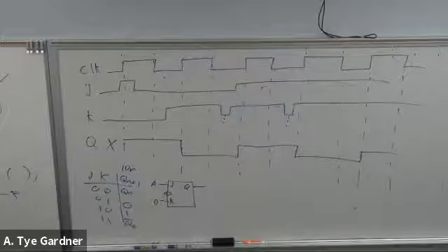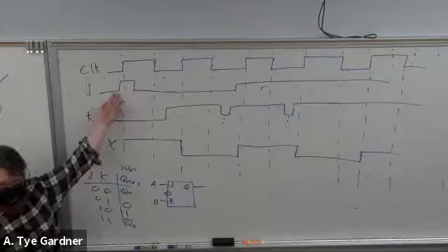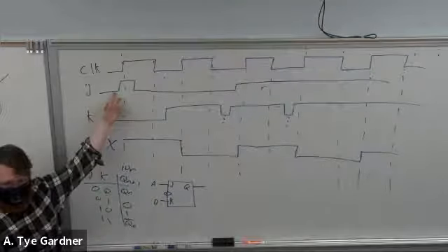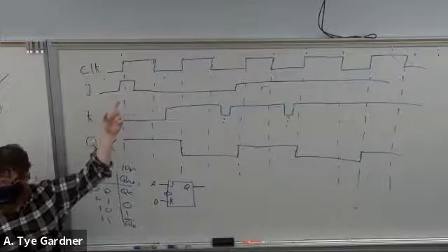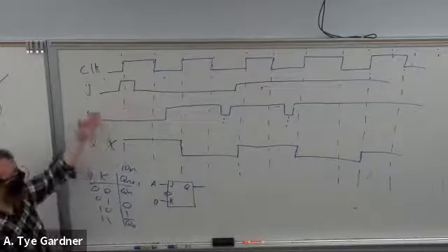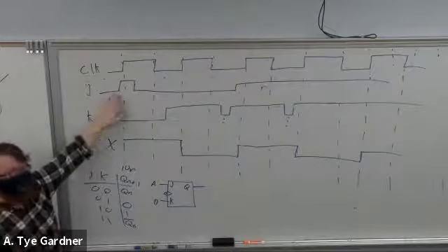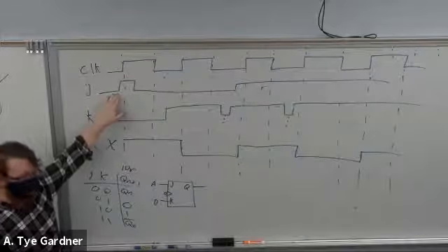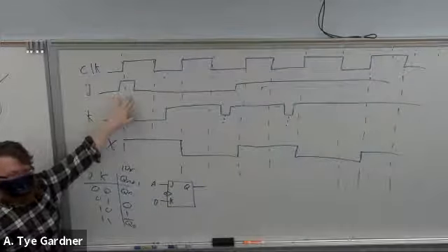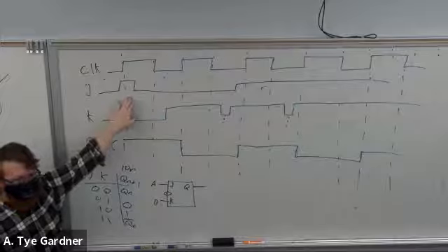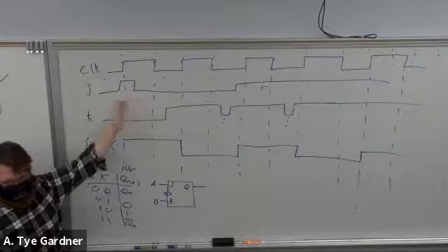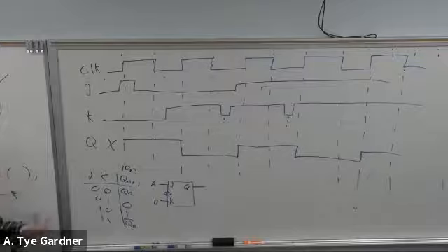Right, and what I'm looking for is setup and hold time errors with that question. Remember the setup and hold time. Setup time being the time that is required for it to be the value you want it to be before the rising edge. And hold time is the amount of time that it needs to stay there after the rising edge. Right, just remember that those are errors. There are issues that you might have.